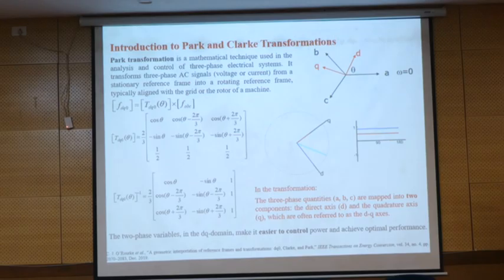So basically the equation we have is V reference equals the square root of VD squared plus VQ squared. You can see from here, this is our reference value, this is VD, this is VQ, and we have 90 degrees between them.